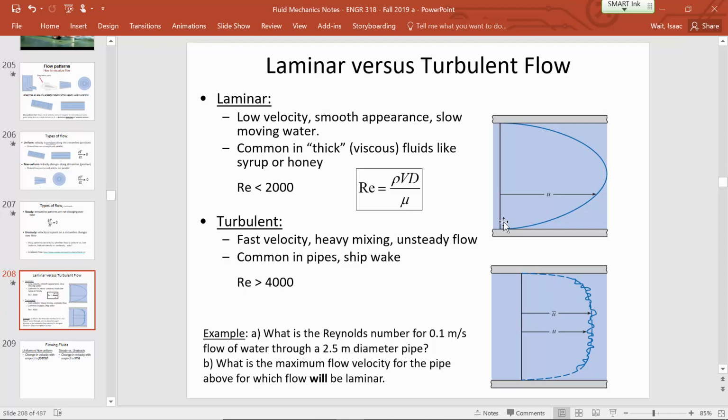It's stationary. And so there is a section that's laminar, which you can think of as a cushion that goes around the outside edge of the pipe, where the flow conditions are low enough that you have laminar flow inside that outer ring of fluid on the edge of the pipe. How thick the laminar region is depends on the velocity. If you have a really slow-moving fluid flow, then that laminar region will be very thick.